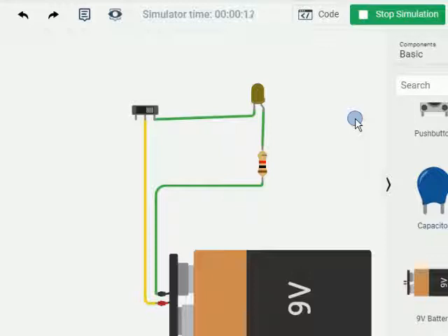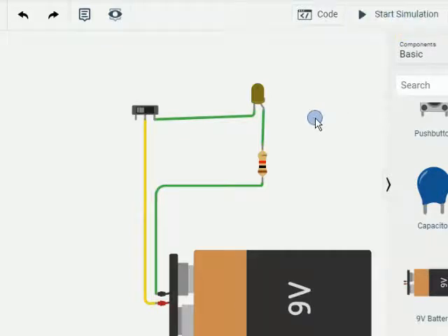Well, because LED stands for light emitting diode. That means it's a one-way check valve for electricity. Okay, so the electricity can only flow in a certain direction with an LED light and in any diode, and it has to be polarized correctly. In other words, the positive and the negatives have to be properly connected. So to show that, I'm going to stop the simulator so we can modify the circuit.